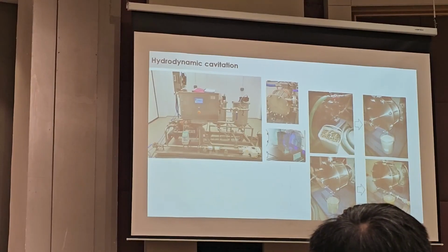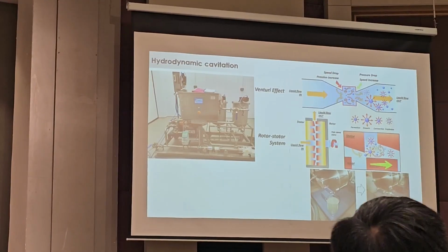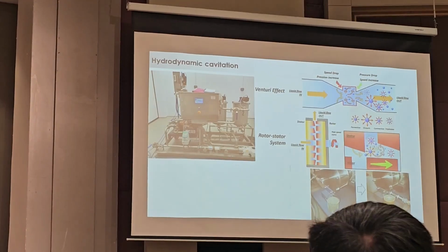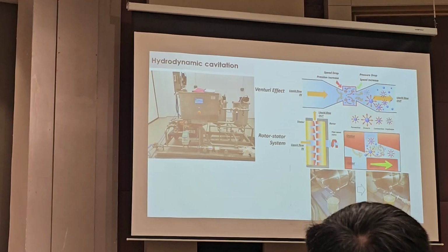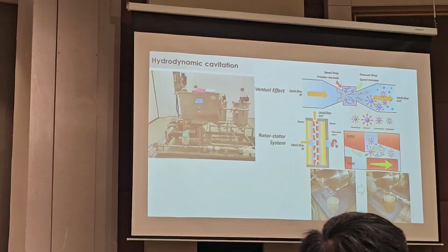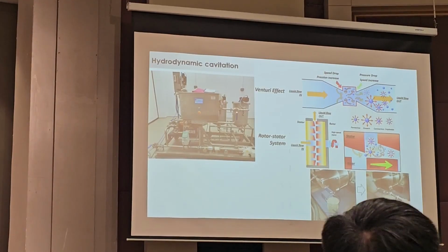Even if you put a solvent, water, you heat it, reduce the particle size. And an example here is two different types of cavitator. One is the venturi effect, that means water is coming with high pressure, you have constriction take place. So you break the water into tiny droplets, which break the biomass. This is what it is all about, the formation of cavities. Then there is the rotor and static type. Either this is static and this moves, or both move in opposite directions, or there are different numbers of patents related to the cavitator.